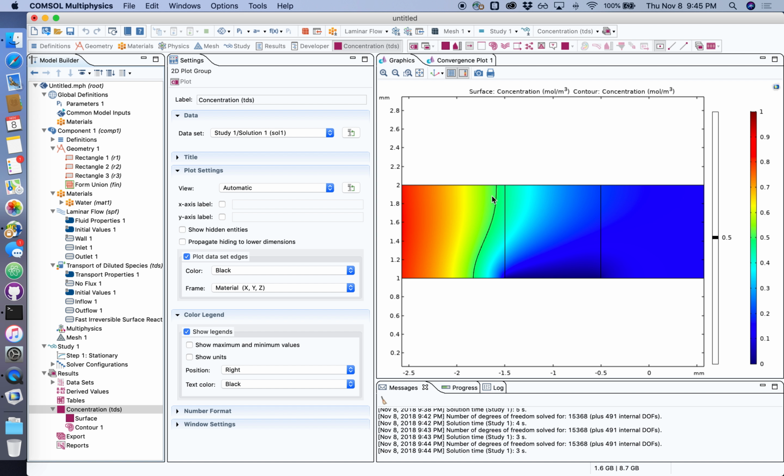slow that convection is losing, diffusion is winning, and our slow transport of fresh target molecules here is being, if you will, beaten by the diffusive-based transport of the molecules to the sensor surface here where they are captured. And that's why this line is actually moving upstream, and we see the rainbow color scheme actually to the left of the sensor here. So now, just like in the first video, we've transitioned into a regime where we have no longer a planar or a radial depletion zone, but now a linear depletion zone. Linear meaning that it's marching down the line of the channel to the left.